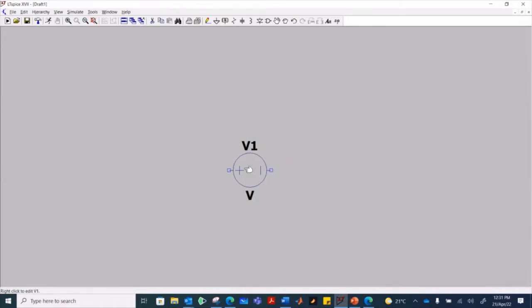What I'm doing now is zooming a bit out. Next, you're going to draw your wires, or conductors, and you click on that. Every time you want to sketch the wire, you click, and every time you want to change direction, you click again. What's cool is that the software lines up where all the wires are for you, so that you don't miss particular points. I'll stop there, Escape again.